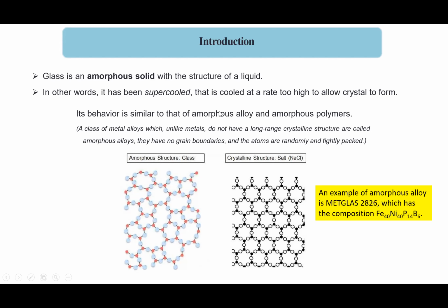But in the case of glass, or in the case of metal, if you cool it very quickly, for example, hardening of steel, what we do is heat the steel to a temperature of around 800 to 900 degrees Celsius to form austenite, and then we suddenly cool it in a liquid bath, that means a salt bath, to get the highest cooling rate.